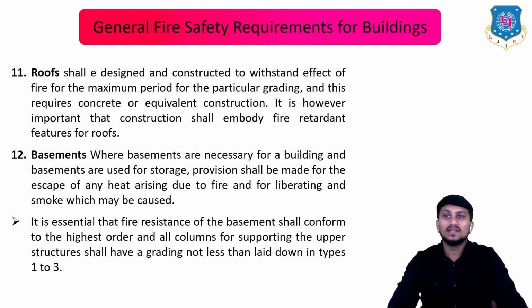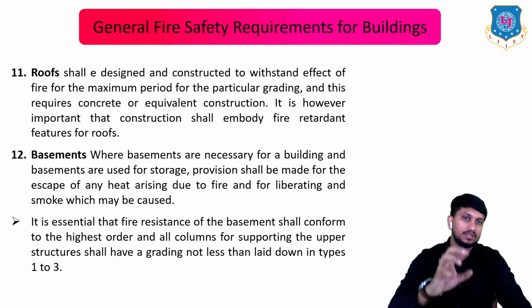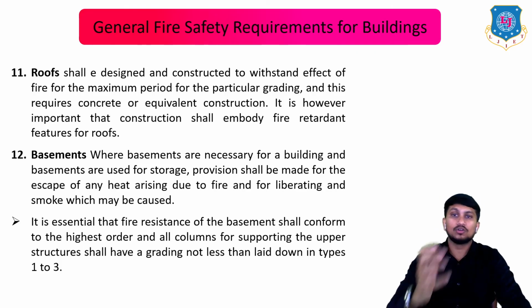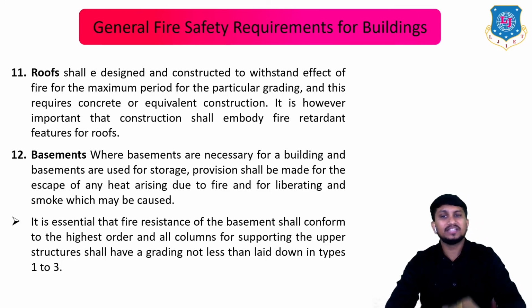Okay, roofs. Roofs shall be designed and constructed to withstand effect of fire for the maximum period for the particular grading of the building, and this requires concrete or equivalent construction in the roof. It is, however, important that construction shall embody fire retardant features for roofs also.